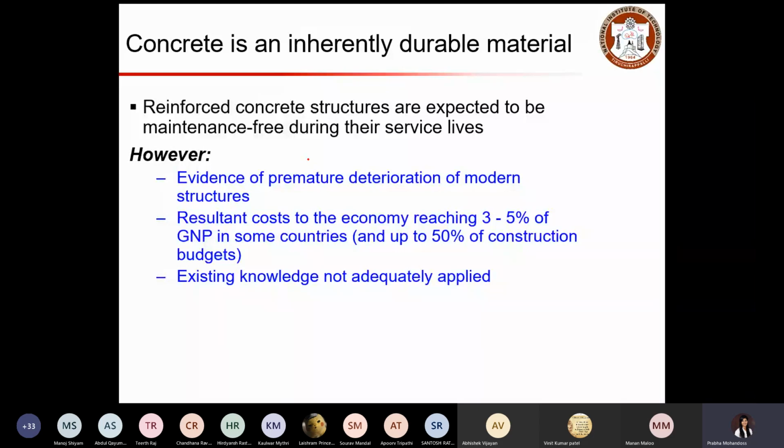But in recent times, the materials that we use without awareness of durability, just checking the cube strength, and if you use such concrete in construction, you tend to observe a lot of premature deterioration. You might have seen this kind of structures in bridges where you pass by, some structures deteriorating because of some issues. Maybe that would be due to poor concrete usage, or the structure was not constructed using durable concrete. And then the cost involved is also high.